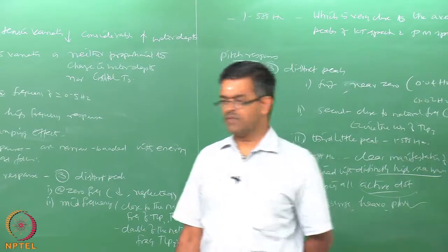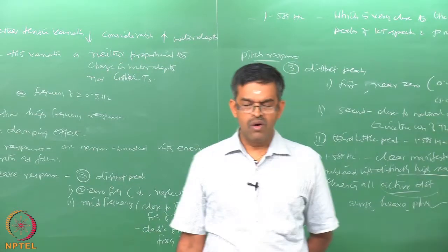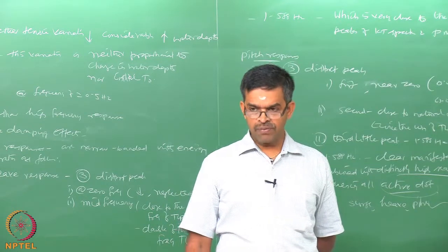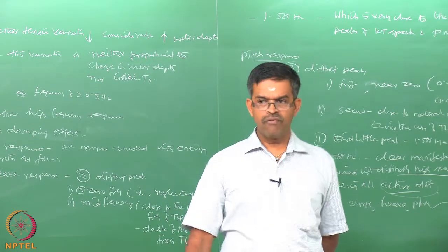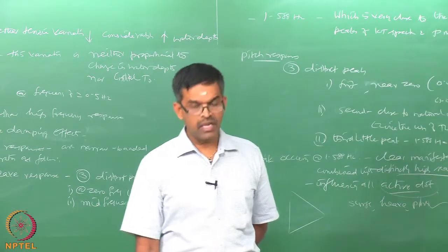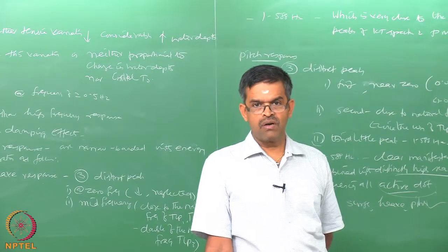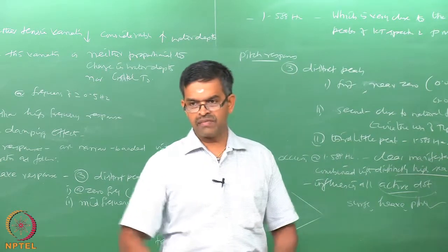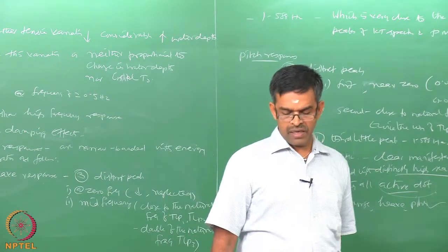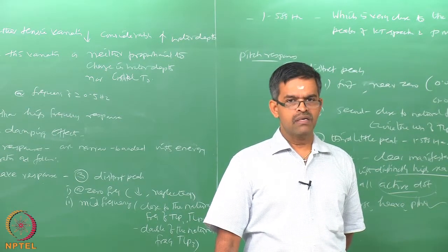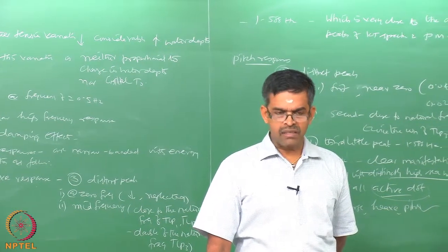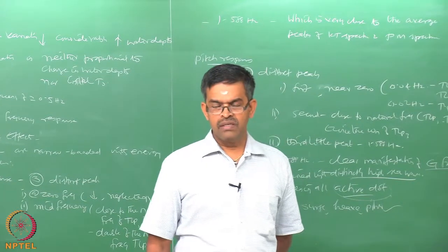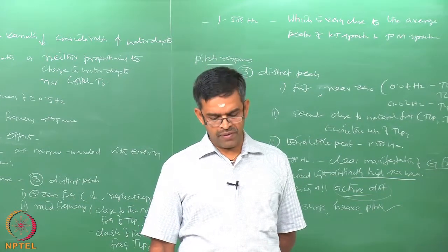So, for a given combination of distinctly high sea waves and earthquake forces generated, one can check the stability and safety of a given system under the worst combination, and the phase plot shown as a typical response of the TLP for this particular combination of forces shows they are elliptical in nature, which confirms that all states are stable and periodic. Of course, the period is longer because the major axis of the ellipse is longer. So, from the example study, one can easily understand that dynamic tether tension variation can be checked under exceptional combinations to check whether this combination would challenge the safety of the given system.